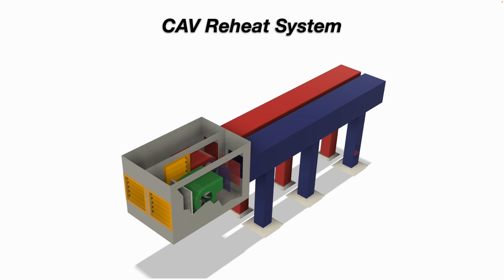So the blue duct is your supply ductwork. The red ductwork, that's your return. So the return air then gets sucked in through that red ductwork via the return blower, and it either blows the return air outside, or some of that or all of that return air, depending on if you're heating or cooling, will flow through this diverter right here on the side between these louvers, and will mix with the fresh air, and then the process repeats itself.